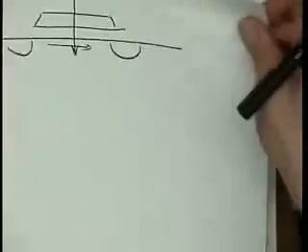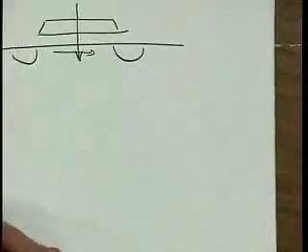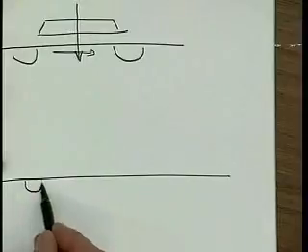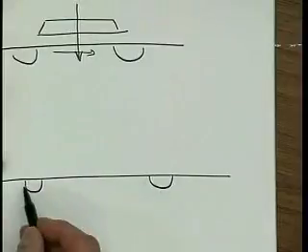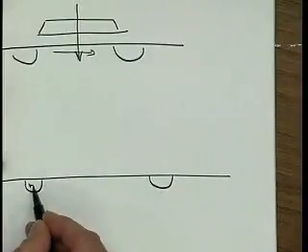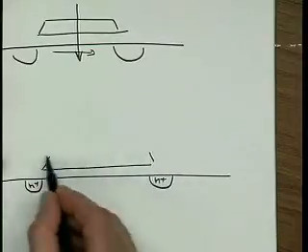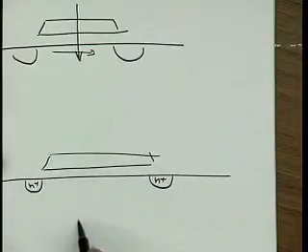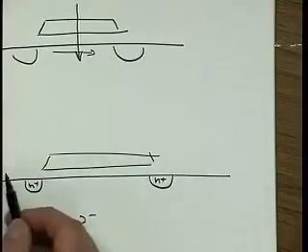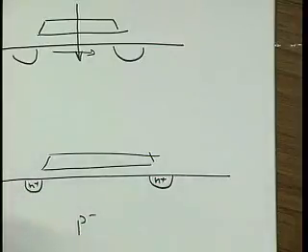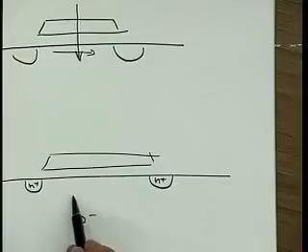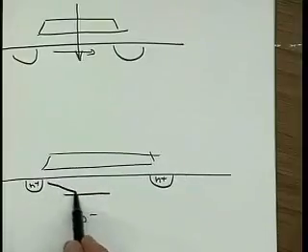What is this n? Well, if we look again at our cross-section, I find those really handy. Let's say this was an n-channel transistor, so n plus, and in the middle we have the channel. Our substrate is p-doped, so we really have an n-p-n transistor. This thing really is like a bipolar transistor.